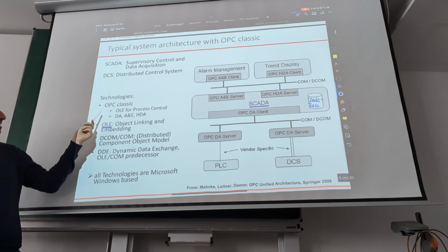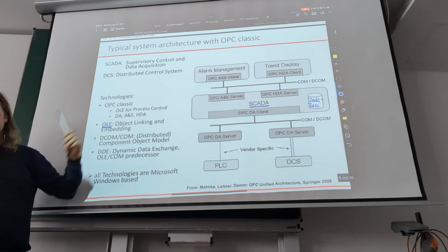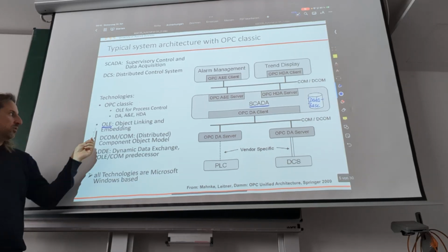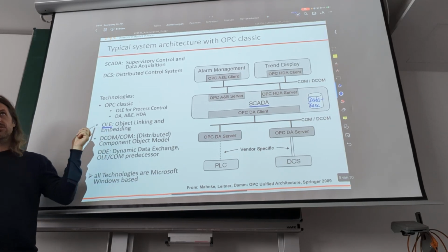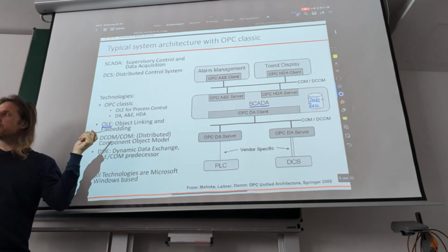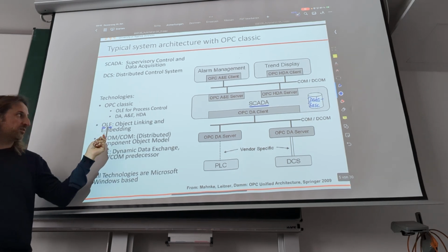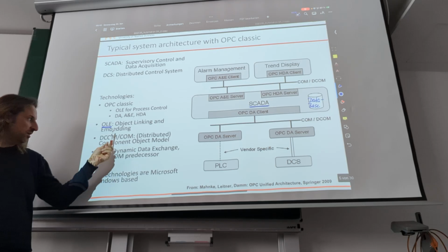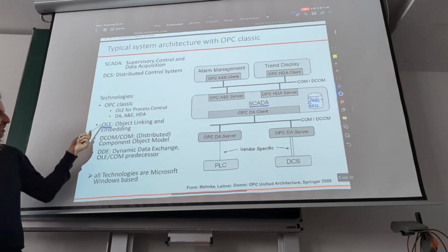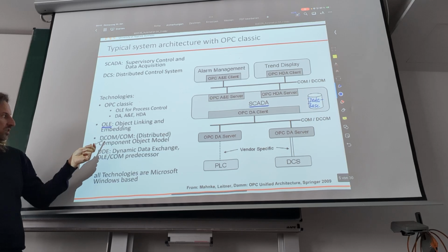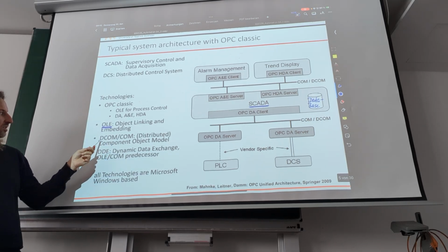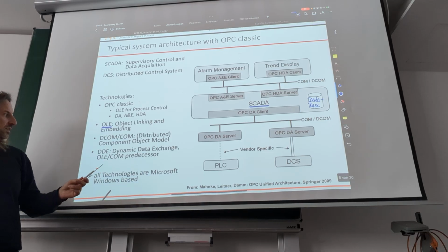So that was the idea behind that, and that's why OPC was OLE for process control, so using that technology for process control. By now that technology of course is gone, and OPC was called Openness, Productivity and Collaboration, and then I don't know the current naming. But basically it was all done with Microsoft technology. So OLE is a Microsoft technology, and it uses COM-DCOM in the Microsoft world to actually do the communication.